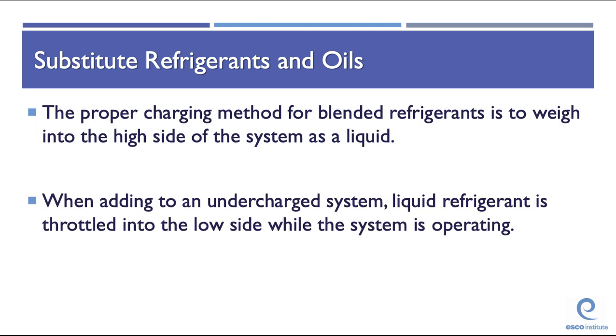The proper charging method for blended refrigerants is to weigh it in on the high side of the system as a liquid. When adding refrigerants to an undercharged system, liquid is throttled into the low side while the system is operating. You never put refrigerant into the high side of a system while it's running.